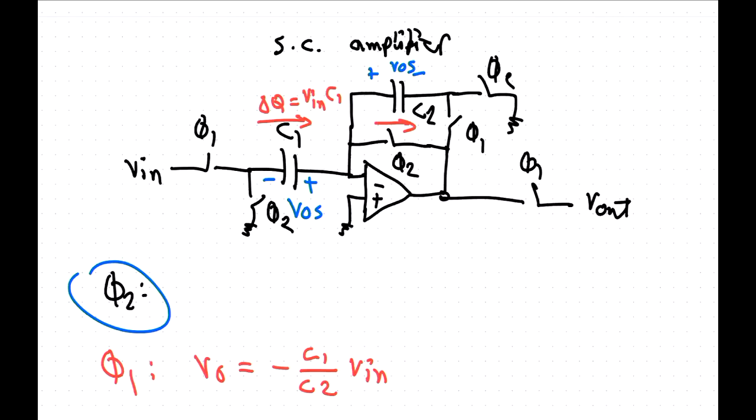If you're designing in a 20 nanometer process, you use the 1.8 volt transistors, and they look pretty much exactly like they did in a 180 nanometer process. You use those for the circuits where the analog function really matters, so you don't gain a lot from going digital there.